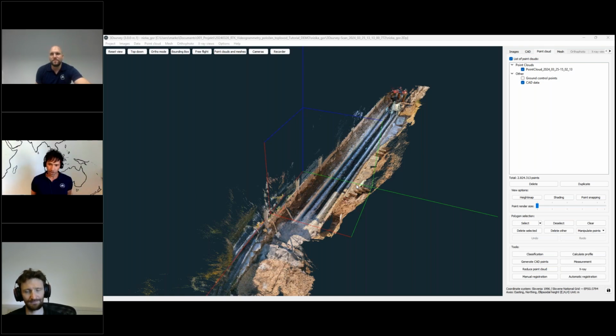What I would say, if we are talking about automatic registration, is that the basis for automatic registration is planes. The algorithm works super nicely if you have 3 different planes, like a horizontal ground plane with asphalt, and then maybe 2 planes for the building facade, which are perpendicular or not. If you have this kind of condition, the algorithm works perfectly.